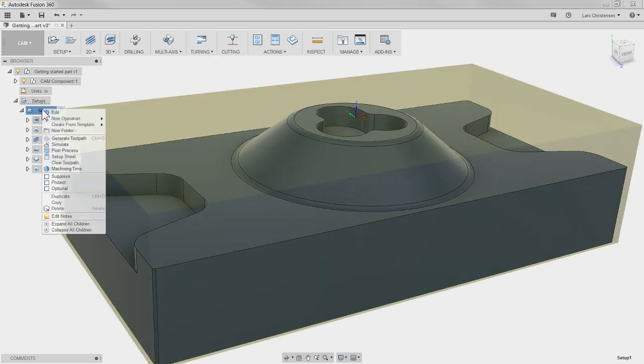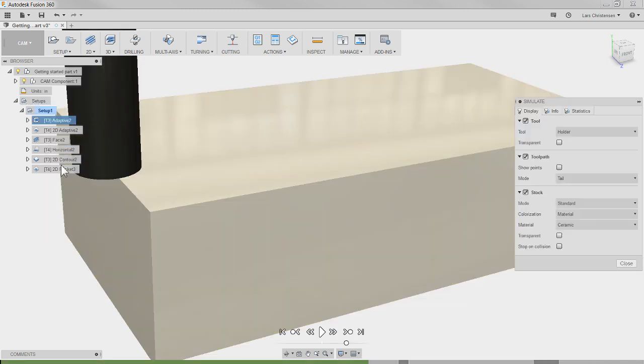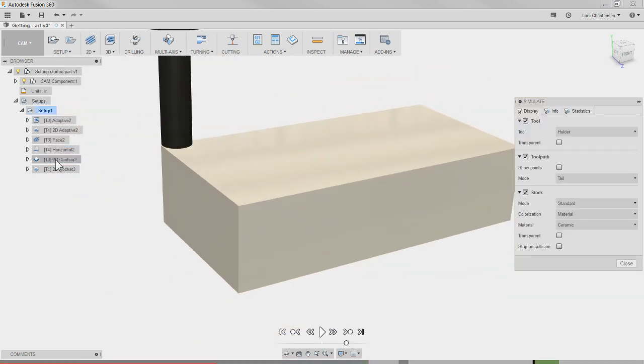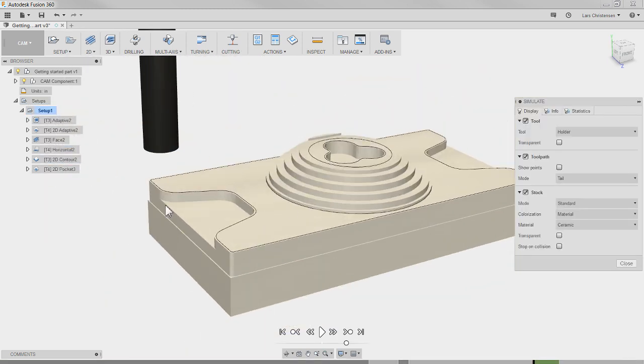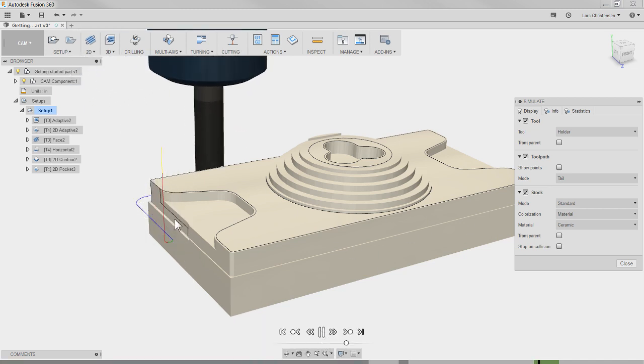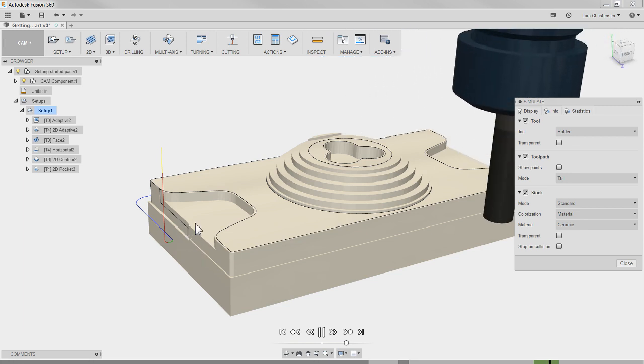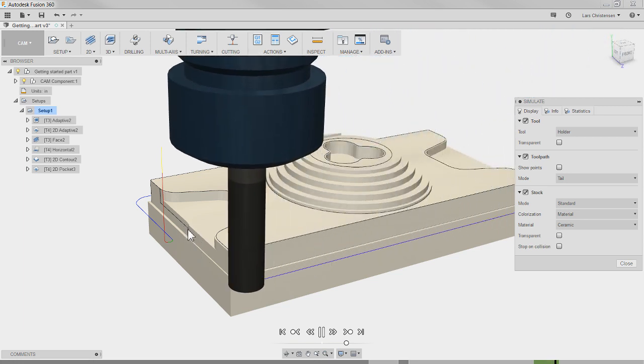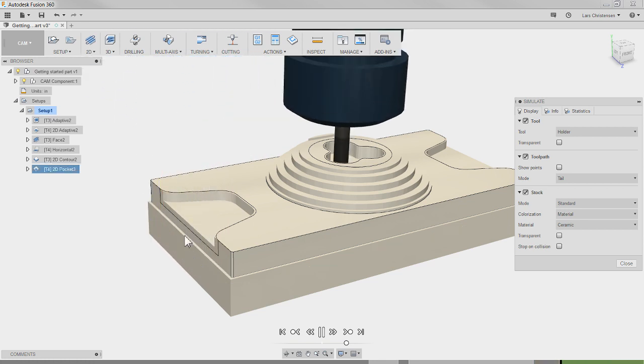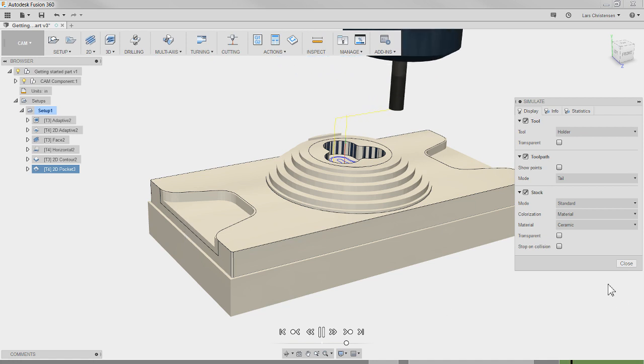So I don't know if you ever run into this. Maybe a bunch of you already do this. But when we get to this contour toolpath, just to clean off the outside, you see how it's starting right here on the center? And then it's going to end on the center of that block again there. It always leaves a little mark right there, right? The cutter comes in, it just sucks the cutter right there.